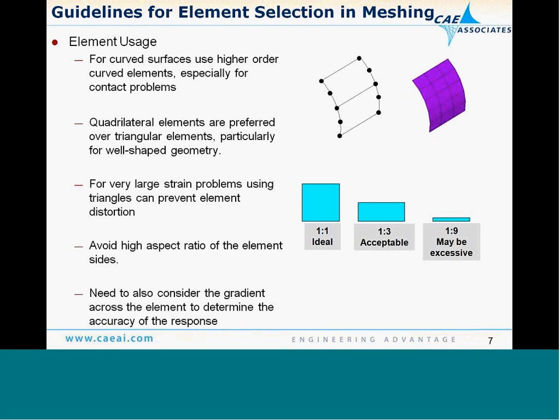If we look in general between the different options of using the lower order elements versus the higher order elements, there are a number of functionality improvements that we gain from using higher order elements. One of them is true curved surface representation of our structure. So in general, we can use fewer elements in the higher order elements than we use for lower order elements.